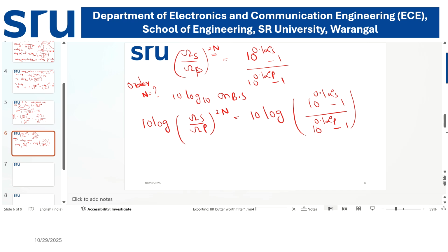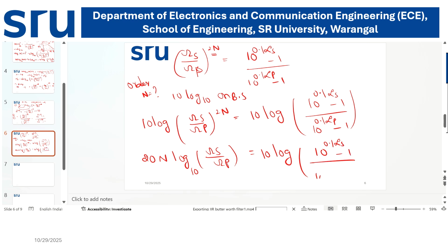Then this 2n I can write as 20 n log of omega s by omega p is equal to 10 log of 10 power 0.1 stop band attenuation minus 1 divided by 10 power 0.1 pass band attenuation minus 1.